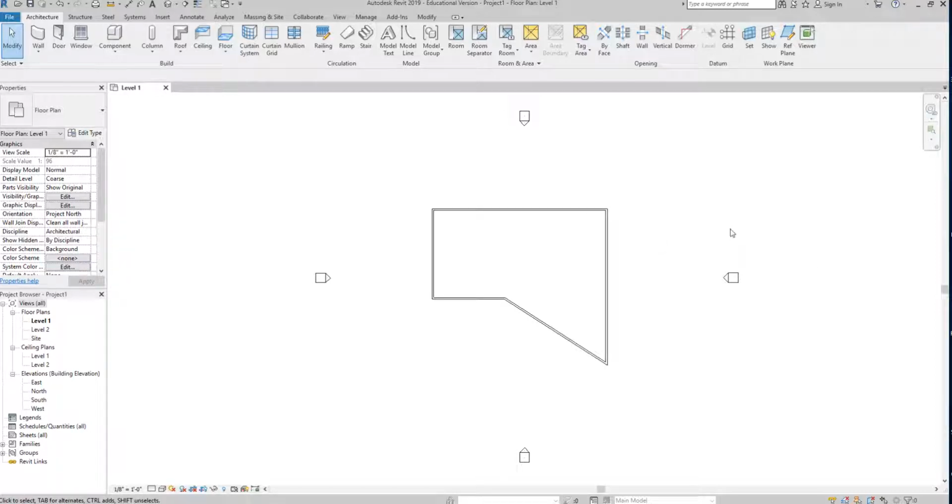Okay, and what the term template means, if you have never used any computer drafting software, is that a template is a file that has a lot of preset items in it that are applicable to whatever your task is, right? So I opened up the architectural template, which means that I'm going to have a lot of things in this file that are defined to create an architectural project. Right? So I'll have predefined windows and doors and wall types and floors and roofs. Okay. I'll also have views of my model created that make sense for an architectural project.